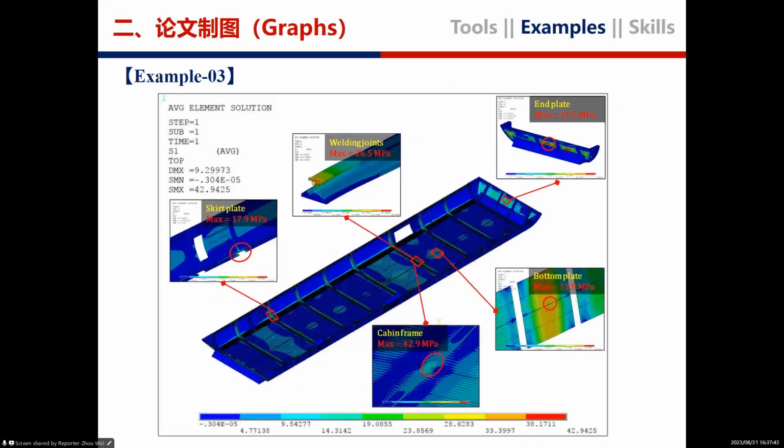After simulation, the equivalent stress at different components must be given in graphs by using the same main window and sub-window to denote the overall stress distribution and the maximum stress as well as its locations for components. So this PowerPoint-made graph is clear enough to include all necessary information for readers or reviewers.